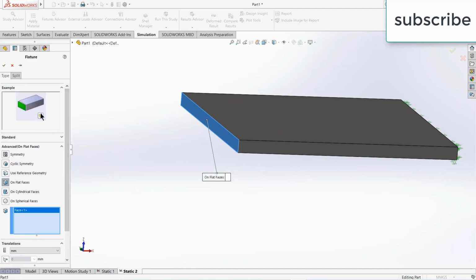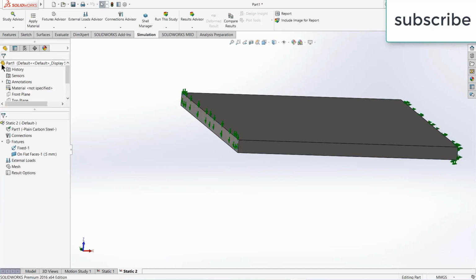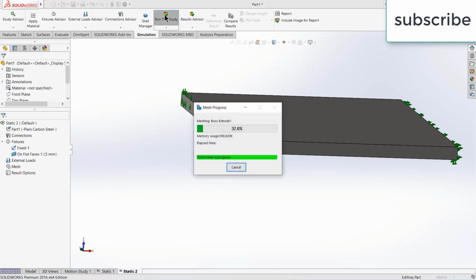Now let's see what these things do. As you move up, you can see the animations showing what these things do. As you can see, these are showing upward, downward and lateral. Suppose I click on this and enter a value of 5 mm. Basically what it means is that this face will move down 5 mm. Okay. Click on OK. Click on run the study.